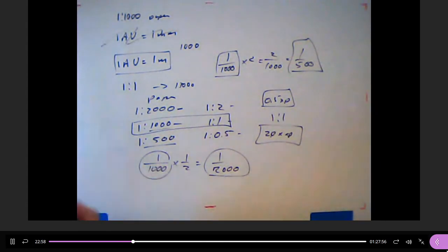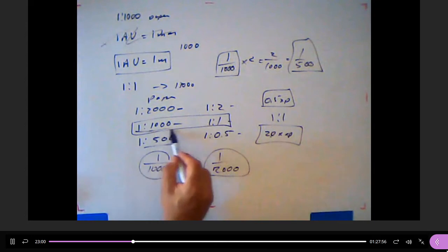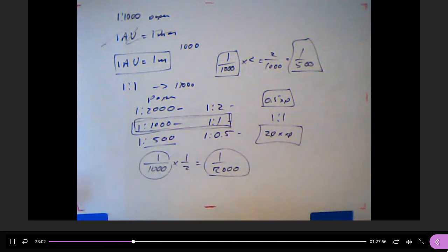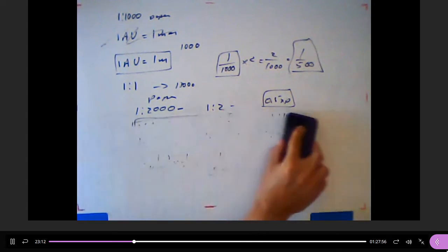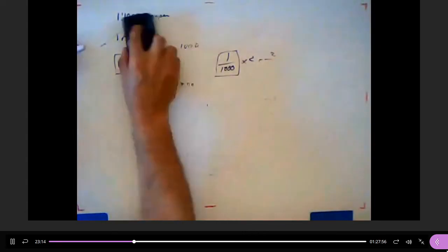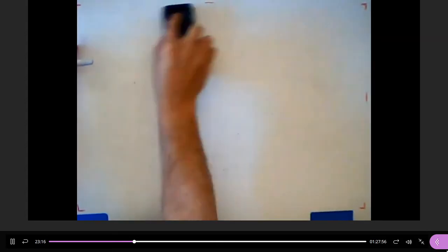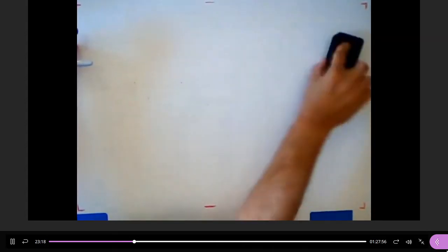So we're going to manipulate the zoom factor, not the plotting scale. We will always plot at 1 to 1. The good news is you don't have to do anything. Just open your drawing and print it. You don't have to change any of the settings. All you have to manage is the zoom factor, by choosing the appropriate scale that you want from that list that I showed you, and I'll show it to you again. So that's a little lesson on scale, if you haven't discussed that in another course, or in this detail. Let me go back to AutoCAD and show you that again.